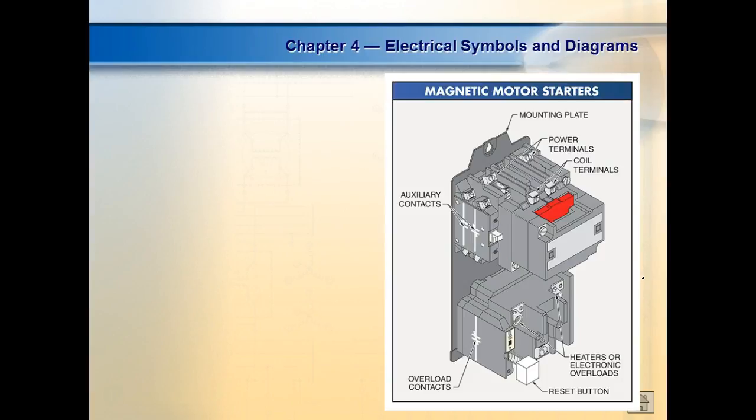They're protected if it stalls or if it doesn't start, or if it takes too long to start. And so your house does not have motor starters in it. It's got contactors. If you went out there and looked at your HVAC system, those overloads are built into the motor.